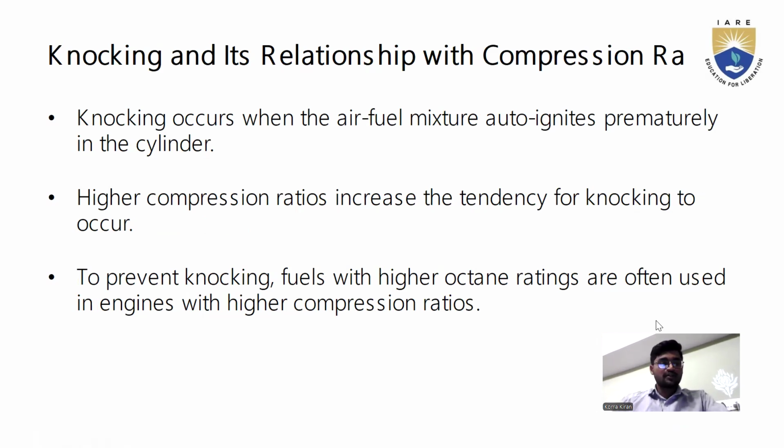Here we can observe knocking and its relationship with compression ratio. Knocking occurs when the air-fuel mixture auto-ignites prematurely in the cylinder. A higher compression ratio increases the tendency of knocking to occur. To prevent knocking, fuel with a higher octane rating is often used in engines with a higher compression ratio.